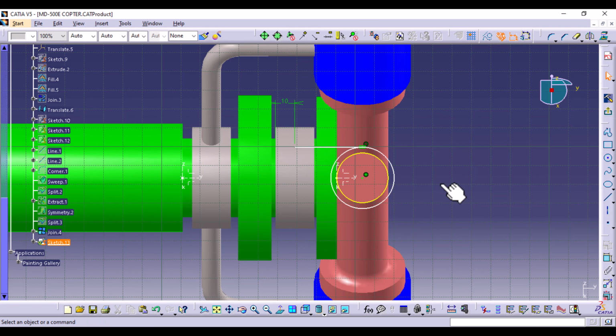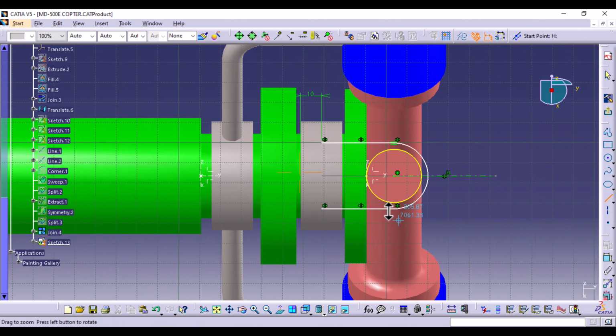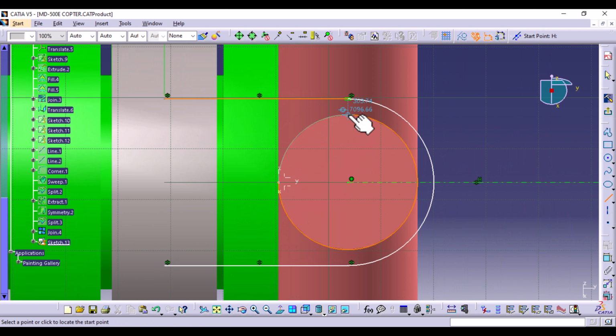Then create an axis, and then select this line and symmetry, mirror it using that. So you can trim off that element. Repeat the same for the inner circle. So make sure you see a blue line that's connecting the middle, or that's connecting to the initial line.